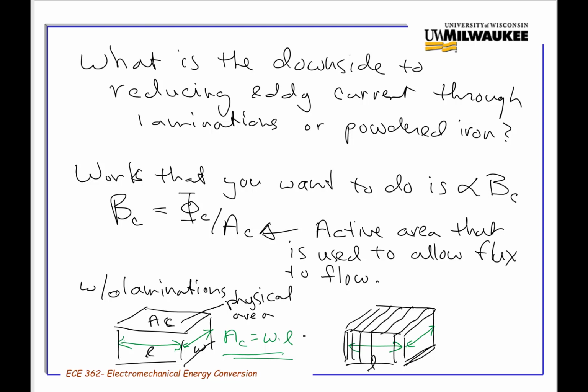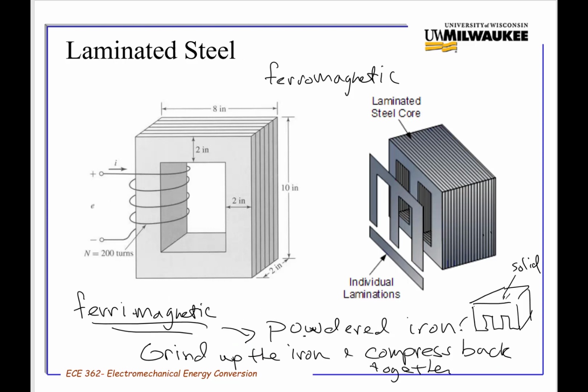So the laminations stack up in the L direction. And that corresponds to, if I look at this picture right here, the physical area of one of these legs, W. That's your core area.